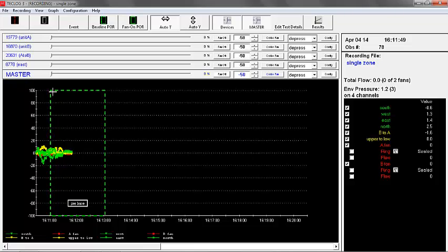The master control slider is going to cruise on the average of the 4 envelope pressures. All the green ones are our envelope pressures. It's showing envelope pressure on 4 channels. It's displaying a number and the difference between the highest and lowest number. So it looks like our fans are pretty erratic to start with, but it looks like we've only got 3 pascals difference between the highest and lowest. So that's what that number in parentheses is, the difference between the highest and lowest numbers.